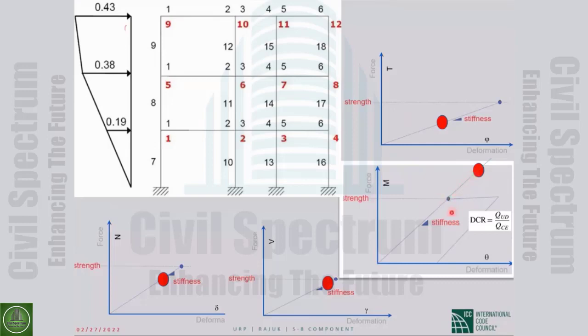This shows damage in linear analysis, that the demand is more than the capacity. The demand is more than the strength. In reality, it becomes nonlinear, and for the level of the ductility that it has, we calculated based on the m factor. So linear analysis can't follow the nonlinear behavior of the element, but this increase can be a good measure or estimation of the damage.